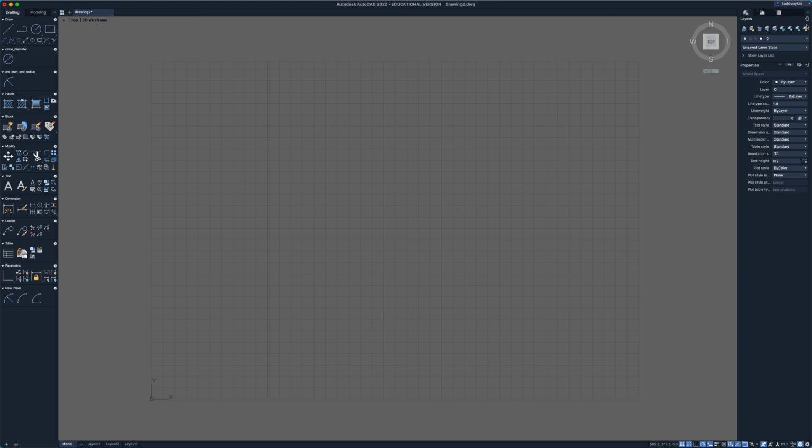Now if I open this little drop down list right here, you can see that beside the center there's a circle. If I now click on that, it makes a sort of an empty circle, which means that the layer is hidden. Now I'm going to go into the properties inspector down below, and I'm going to go to layer, and I'm going to turn on center.